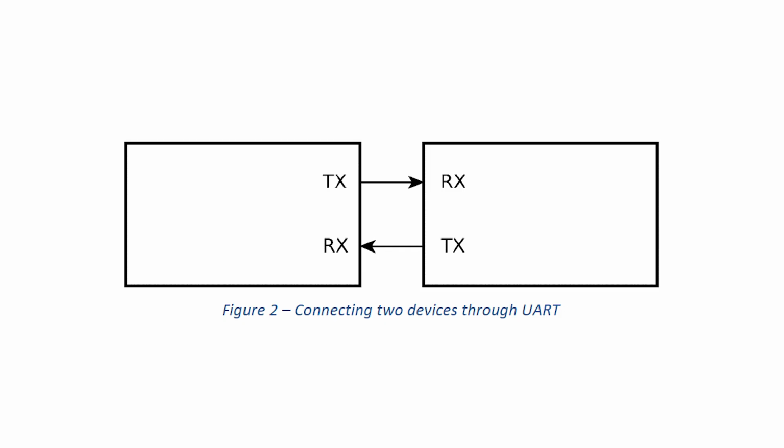Voltage can be measured only relative to something. In this case, voltage level means the potential difference between the ground and the signal line. Both signal lines can transmit and receive data. RX and TX only mean something in the context of a chip, because the TX line of one device is the RX line of the other device. This also means that we connect 2 UART-compatible devices by connecting the RX pin of a device to the TX pin of the other one, and vice versa.